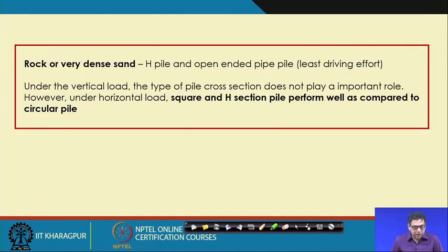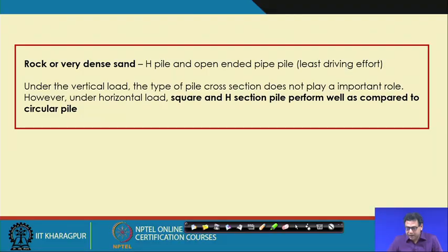And for rock and heavy dense sand, H pile and open ended pipe pile are suitable. And all these examples I am giving are suitable, but this is not the only application. Okay. You can use other kinds of pile also, but this is one of the examples where it is more suitable. So, this is the open ended pile, because here you have to apply the least driving effort.